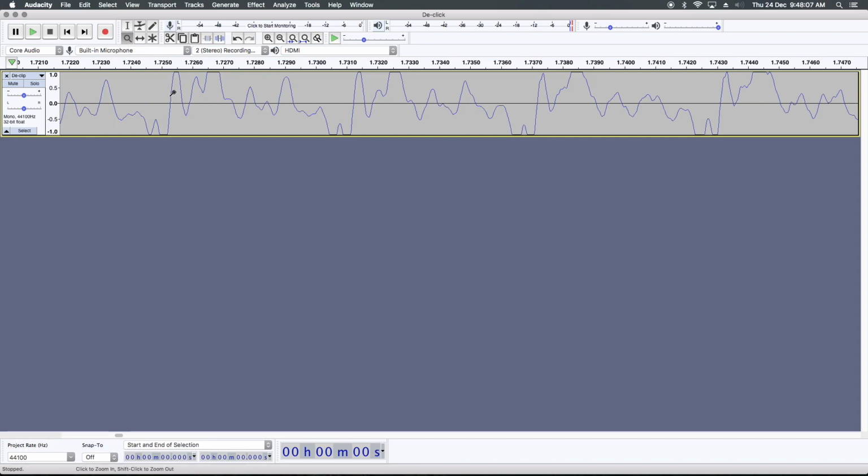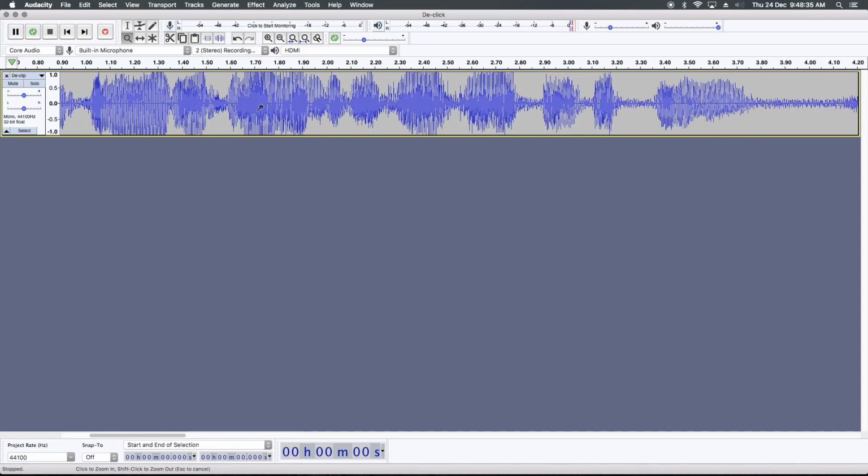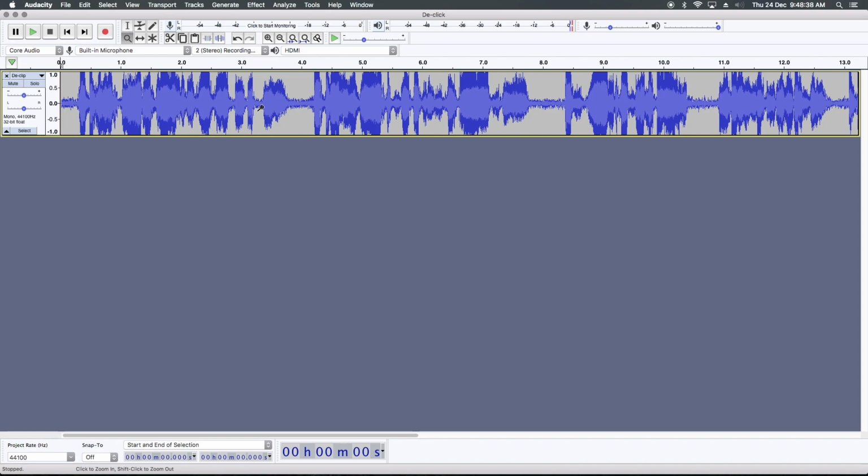So what we have to do is try to make it more even. How can we make it even? To make it more curvy, with more ups and downs, like this is the curve, you can see how beautifully it's coming, but this is going straight. That is why this clipped sound is there. Can we make this audio completely clear? No. But yes, we can make it hearable. This kind of problem is called the clipping problem, when the audio gets clipped over 0 dB.